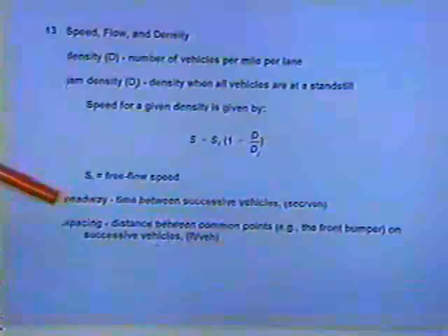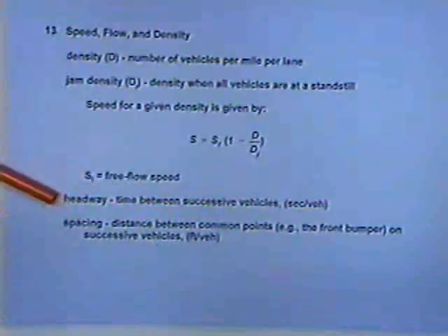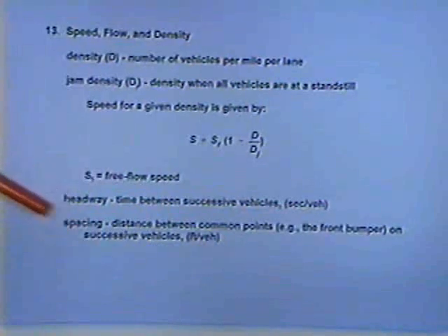So if you know what the volume is, you can compute the average headway between vehicles and vice versa. So there is that relationship. And if you know what the speed is, you can compute what the average spacing is between vehicles.